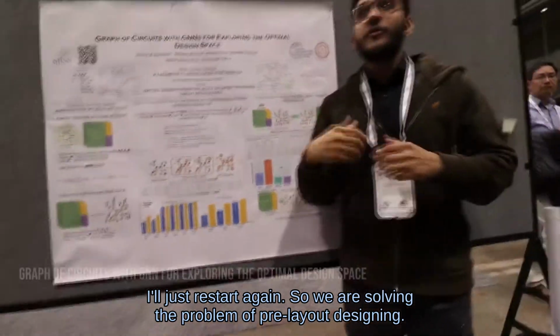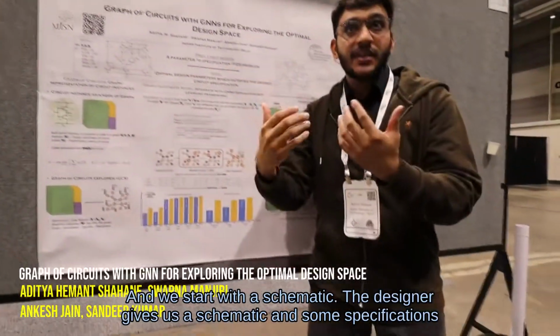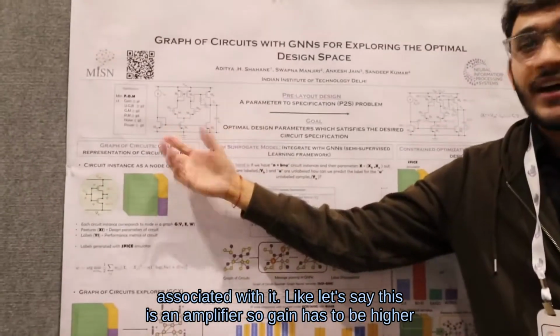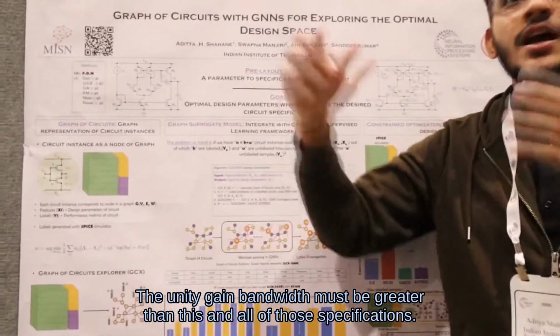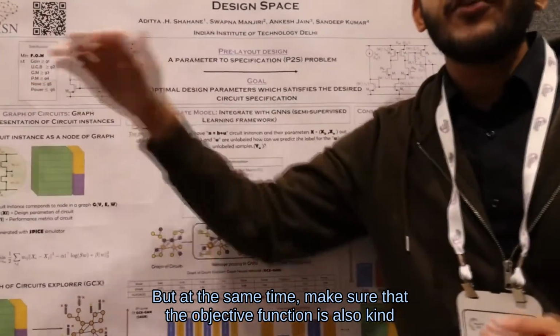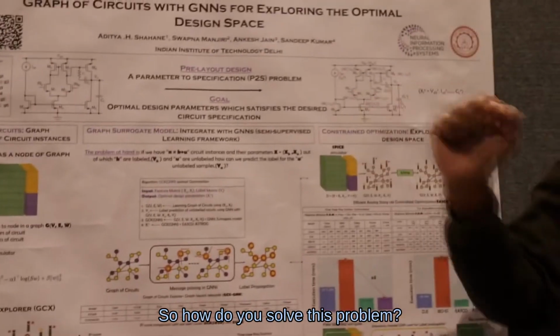So we are solving the problem of pre-layout designing. We start with a schematic. The designer gives us a schematic and some specifications associated with it. Let's say this is an amplifier, so gain has to be higher than this value. The unity gain bandwidth must be greater than this, and all of those specifications. But at the same time, make sure that the objective function is also minimized or maximized, depending upon what the objective is. So how do you solve this problem?